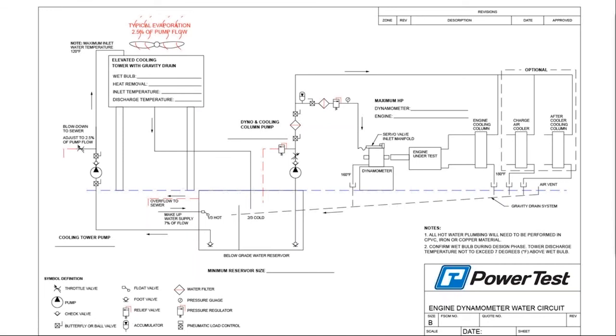And the discharge temperature is directly related to the wet bulb temperature. I think we talked about wet bulb before. Wet bulb temperature is specific to the location that you're in. If you have extremely high temperatures, your wet bulb will be high. If you're along a coastline, along the equator, your wet bulb temperature will be even higher, because not only do you have high temperatures, but you have high humidity.